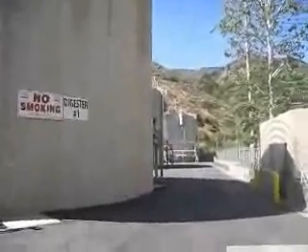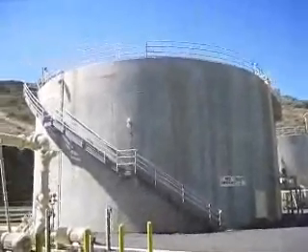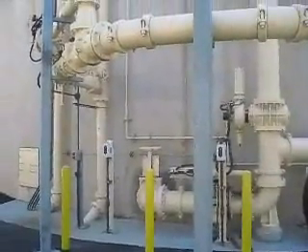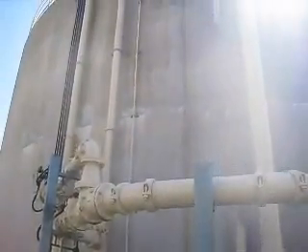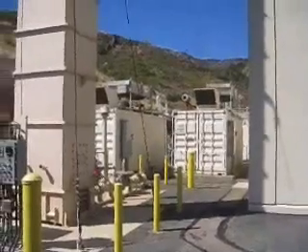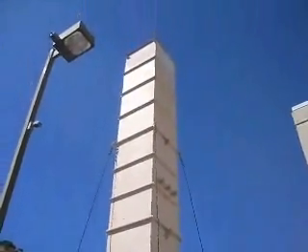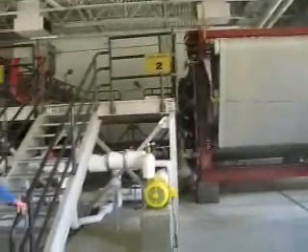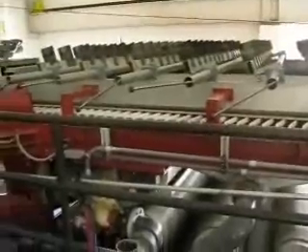Digesters are kept at about 96 degrees Fahrenheit. Inside, anaerobic organisms digest sludge from both the primary and secondary treatment. Methane produced from the anaerobic organisms is used for about half the plant's energy. Cogeneration is used at the plant, which recycles the energy produced by the bacteria. The sludge then goes through a belt press, where 2 belts squeeze out excess water.